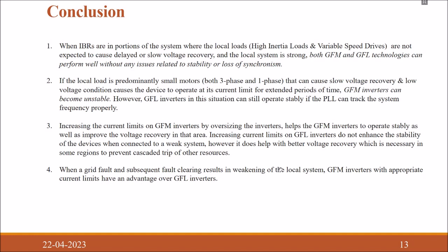So when IBRs are in locations where their local loads are considered, and we don't want delayed or slow voltage recovery, even if the system is strong, both GFM and GFL technologies can perform well without any issues related to stability or loss of synchronism if we have a higher current capacity of GFMs.